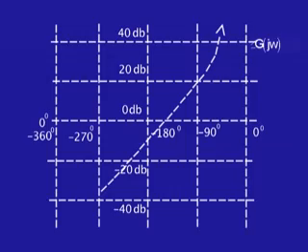This is not that. The z over 1 plus z transformation is still z over 1 plus z, but now one is looking at plotting it in a different way. And now you can ask a question similar to the question that we asked earlier for the gain and phase shift for the closed loop transfer function, where we had the polar plot. Now we have a plot which is no longer the polar plot, and since Nichols introduced this idea, it is sometimes called the Nichols plot.